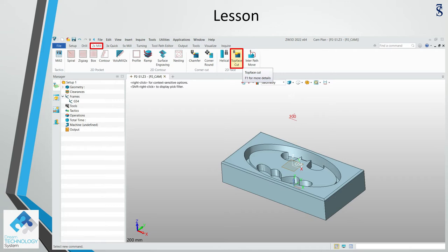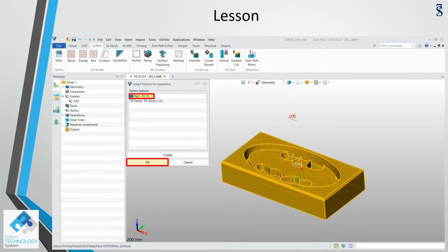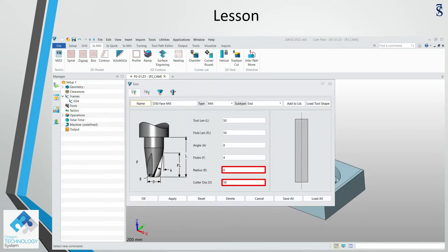We follow with the 2-axis mill, top face cut. That is the standard way of doing a face mill. This round we are not going to create the 4 corners to create features. What we do is just select the part by itself. You can see that this is much easier.